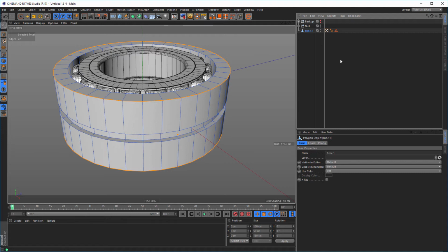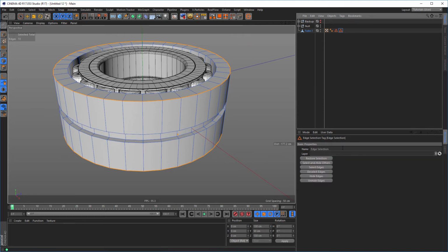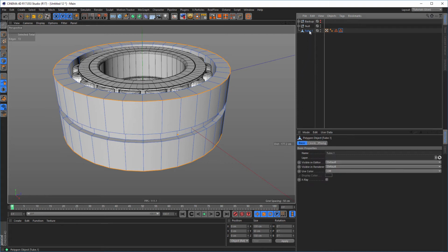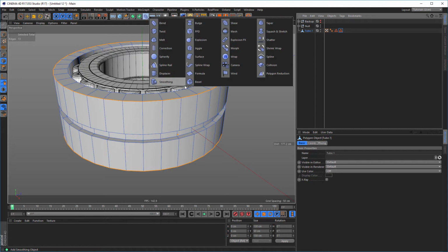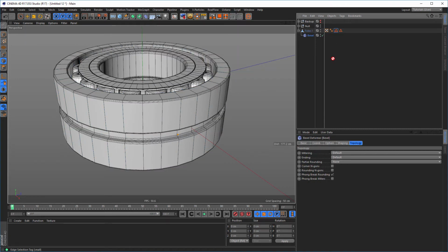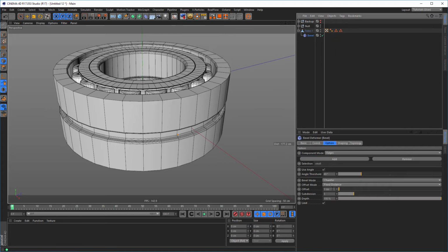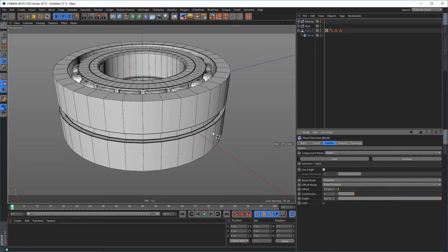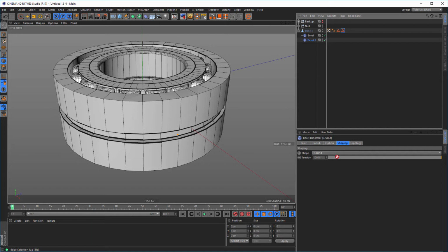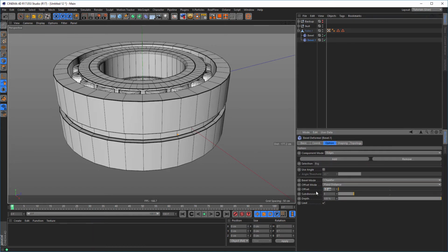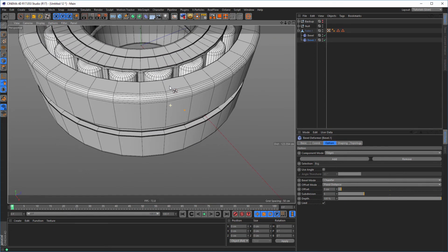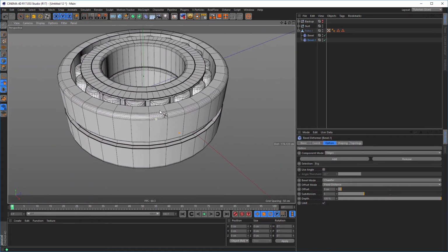But we need a second selection tag. So just click somewhere, then go back to your tube and set selection. This is our big selection now, big rounding. Here I make it with the bevel deformer. I take the bevel deformer, put the small rounding here with 0.3. Then we copy this bevel deformer and put the big one here with maybe 3 and 5. Okay, and the modeling should be ready.